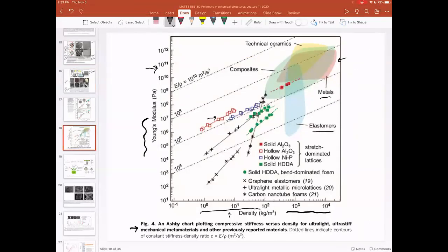And of course, if you make this out of ceramic, you now have a heat resistant tile, like the type of tiles that they use on spaceships, where the ceramic provides the thermal properties, but it's ultra, ultra light and traps a lot of air. And so it has really good insulative or low heat conduction properties as well. So there's all sorts of uses for these types of architecture materials, aside from just making things light and strong.